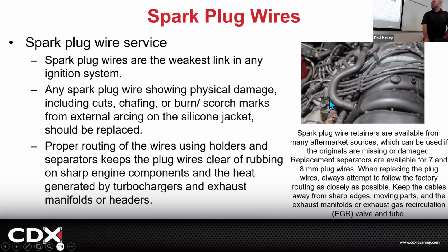If I missed it and all of a sudden I see a little arc right here, you can hear it too. It sounds like a crisp snap. Crack, crack, crack. I'll be like, oh yeah, your wires are no good. How did I test it? All I did was make a potential conductive path to test the insulation. Was it fancy? No. Does it work? I say yes. And then if I do that, I'd be like, yeah, you need wires.